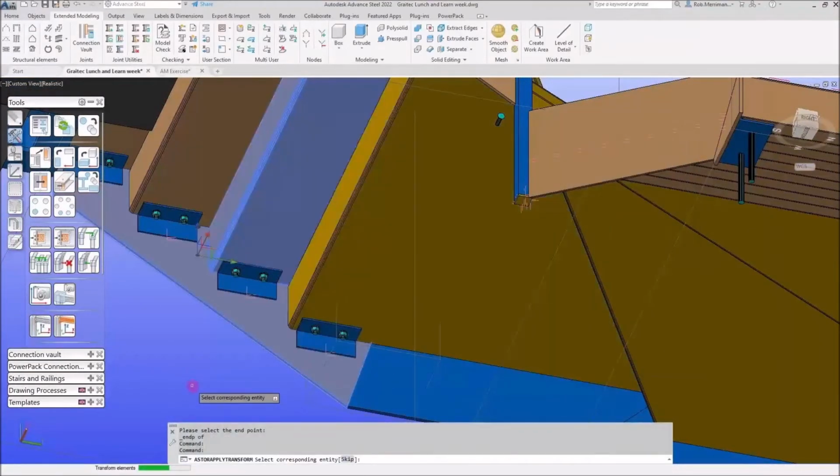Now, this happens quite a lot, so while we've got this, I'll run through this. The system is saying here, you're copying the angle, the bolts and the welds from this stringer and this folded tread, which is a folded beam, to this position here. And if you ever get this green bar, that's the system saying, well, the thing you've told me to copy, I know what it was associated with. Where you've told me to copy it to, I don't know what that is associated with. I can't find the same object because this here is a folded beam. This is a folded plate, and they're different objects. If I click this, it says cannot complete action because mismatching object types.